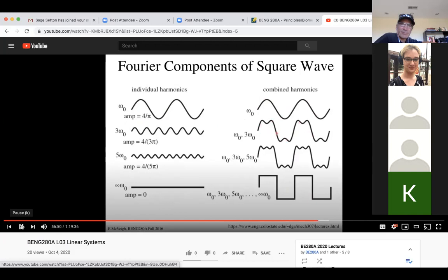but a sharper edge here, right? So the frequency is sharpening up this edge. And then I add another sine wave at a higher frequency, but a reduced amplitude, and you get a sharper edge and more oscillations in the flat top part. And then as this goes on, this is the discrete composition of this function. As this goes on and decays away, but it goes to higher and higher frequencies, you can essentially reconstruct this square wave using those Fourier coefficients, right?